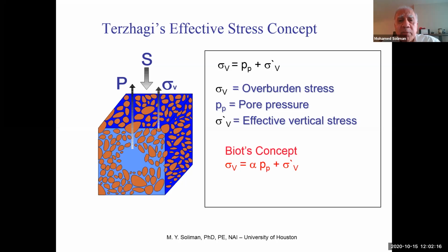The first attempt to look at it was Terzaghi's effective stress. He said that what is being carried by the grains is you just take the total stress and subtract out of it your pore pressure. However, people found out later on that pore pressure may not be 100% effective in carrying that stress because it moves out as you press it.